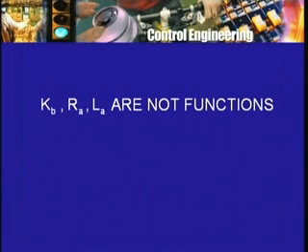IA into RA, again RA is not changing with time. That's one of the assumptions that I am making, of course. In practice, the armature will get heated up, and depending on how much current it is carrying, the armature temperature will vary. Therefore, the armature resistance will not remain absolutely constant. The third term is the derivative of the current multiplied by the inductance, and I am assuming that the inductance does not change with time but remains constant.